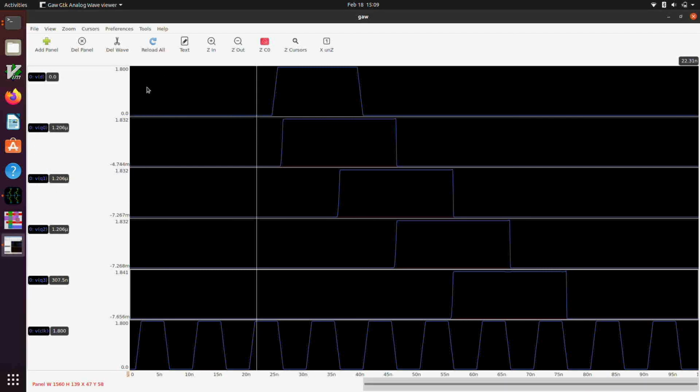So the initial state of all of the shift register bits is 0, and we don't have any extra little bits coming out here, any little pulses coming out from the internal states not being properly initialized. And we have our sequence of 4 successive pulses here that are aligned with the falling edges of the successive clock periods here. Okay, so that's about it.